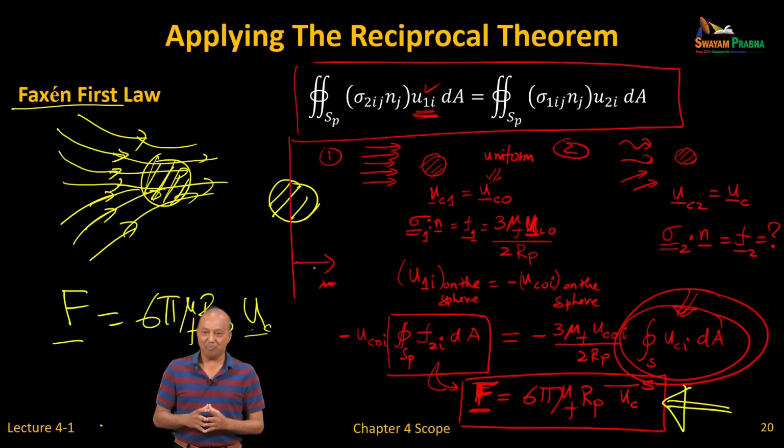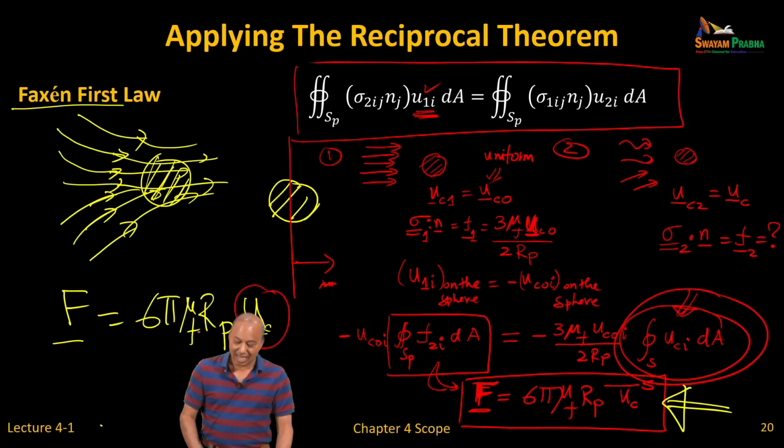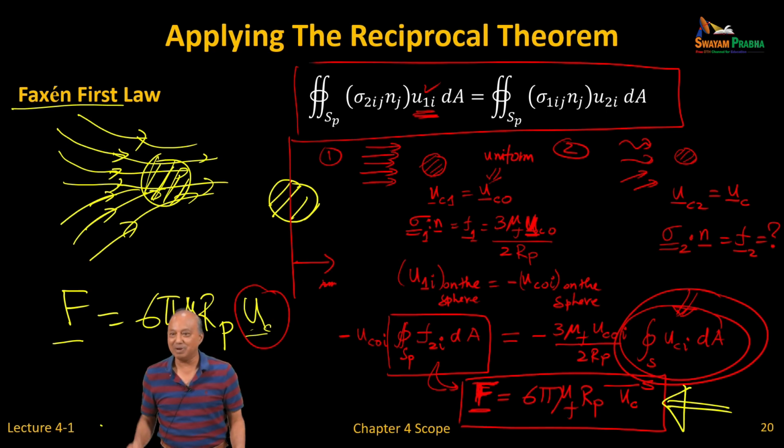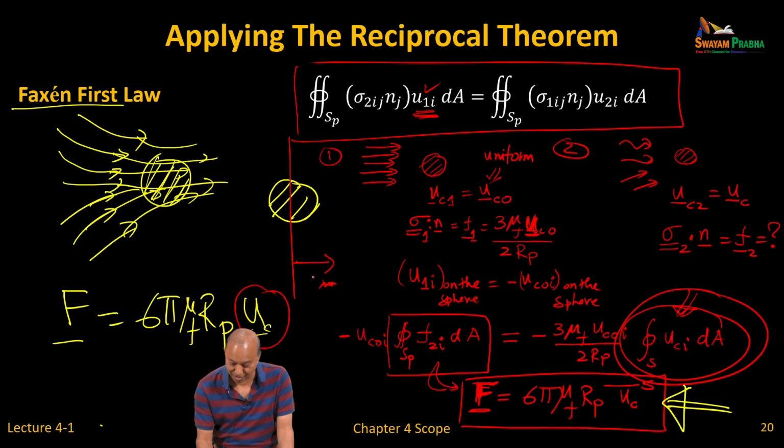So the main point I want to talk about is, when velocity changes on the scale of the particle, what to put? Do I put the velocity on the left or the right, at the top or the bottom, or simply calculate it at the center? Most people just use the center velocity. Now I tell you, that's sometimes disastrous for a shock-particle interaction.